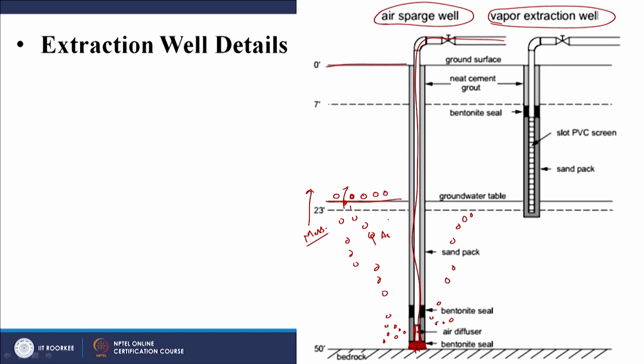Similarly, at the same time, we are going to have contaminated soil here in contact with contaminated groundwater. So, as the contaminant is removed from the groundwater into the gas, or the air bubble, you are also going to have desorption of the contaminant from the soil into the groundwater, right. So, that is something to keep in mind.